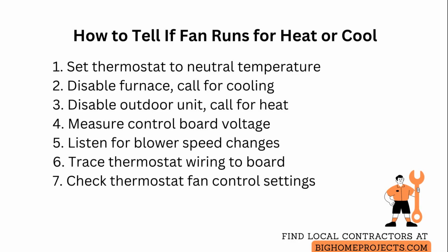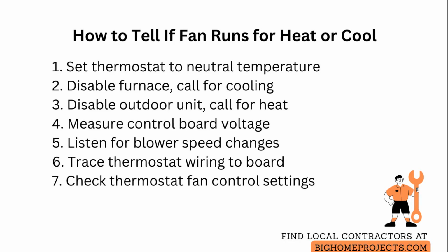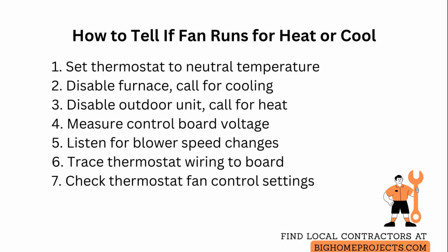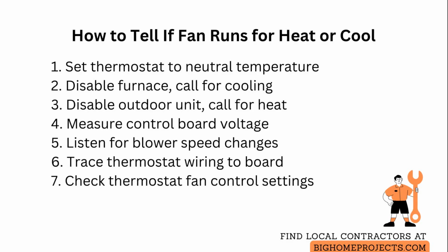For direct verification at the control board, measure voltage between the furnace fan relay terminal and common when calling for heat and when calling for cool. A 5 to 24 volt control signal will indicate which thermostat output is energizing the fan. Use a digital multimeter on the low voltage setting and follow safety procedures.